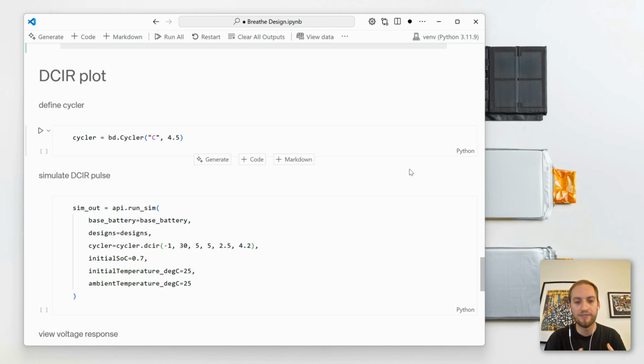But one downside of increasing that electrode thickness is I would expect that I'm going to make the resistance slightly worse. And again, this is where the application and the use case is really important. If I am a high power application, then on paper, higher capacity might actually result in lower runtime if my route to the higher capacity was a higher thickness.